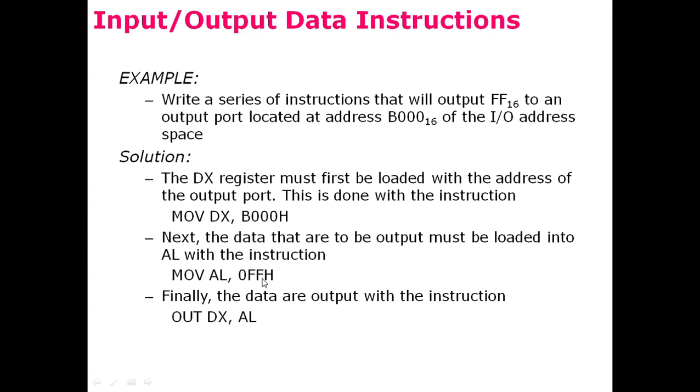If it is a 16-bit value, then it would be stored in the AX register. Then the instruction OUT DX, AL would send the 8-bit value in accumulator AL to the output device with the port address designated by the DX register.